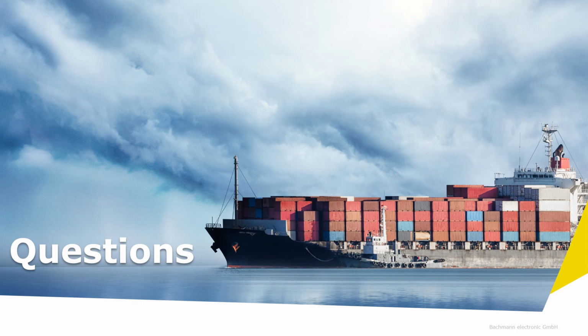We are certainly investigating those capabilities. It's not that straightforward to do. As you might imagine, it's quite an in-depth processing challenge, especially with spectra, because for various reasons, a single spectrum doesn't come from a unique time signal. So we can do some things along those lines, but mainly what we're doing in the Weblog system is picking out a narrow band frequency and using that to detect a specific fault frequency.